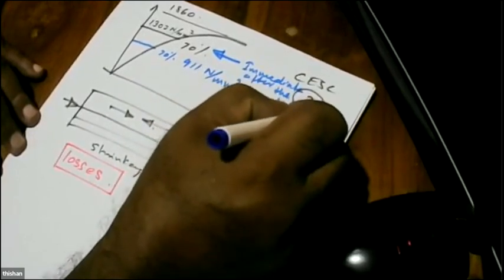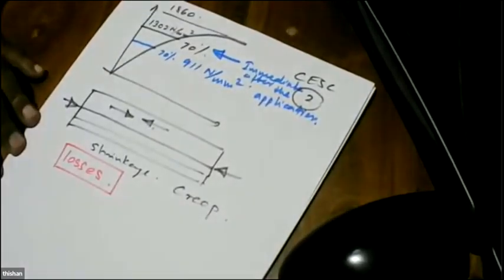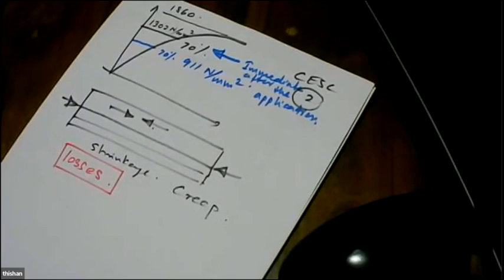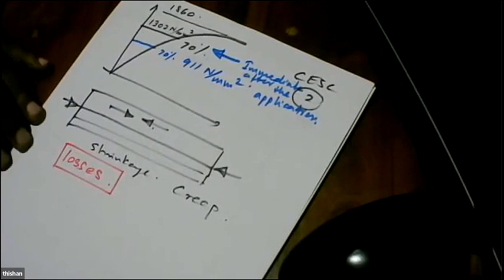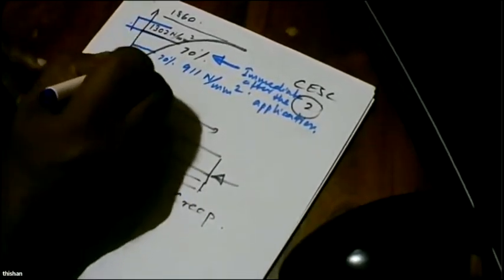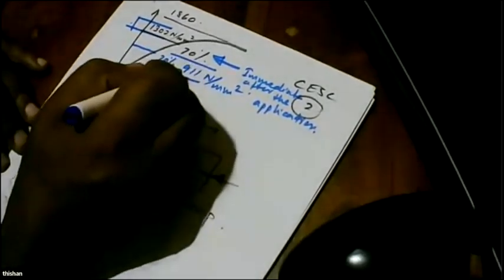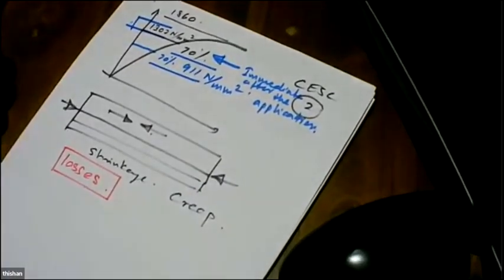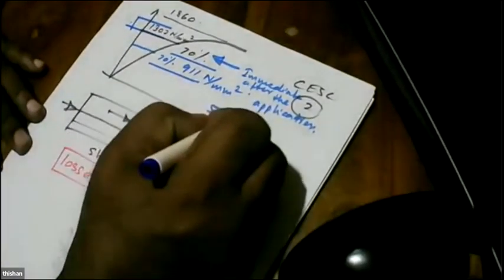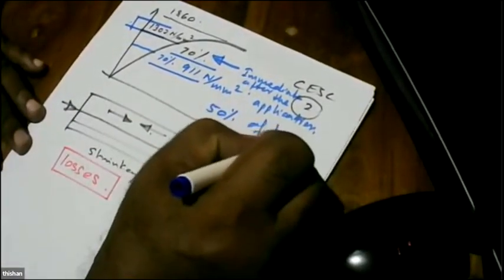As soon as you apply the stress or transfer the stress, if the member does not fail, the chances of it failing later would be much less, because when you are transferring, we are at this level. When you are using it, you are at a much lower stress, around 50% of breakage strength.